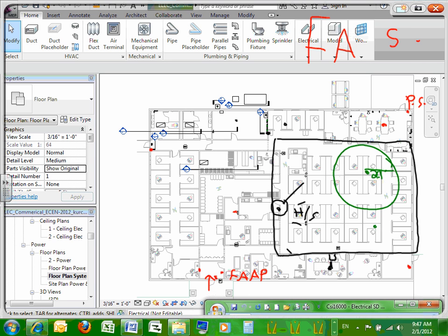So then you're going to lay out your smokes with these circles around them, overlapping. Like Chad said, they should overlap. If they don't, if you've got a tiny little corner that's uncovered, then you either have to shift them or add a smoke. Obviously I'm not drawing to scale here, but you want coverage like this. Everybody got the radius of 21, not diameter, radius? Or 30 by 30 if you're using squares.